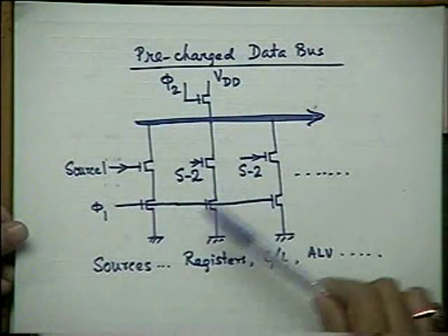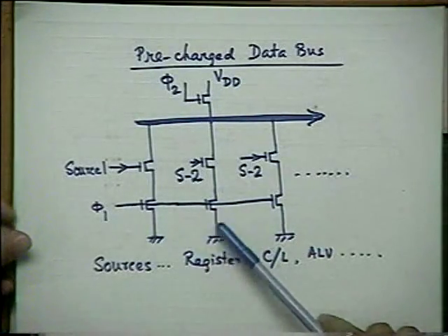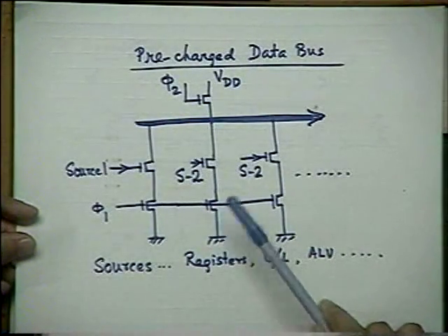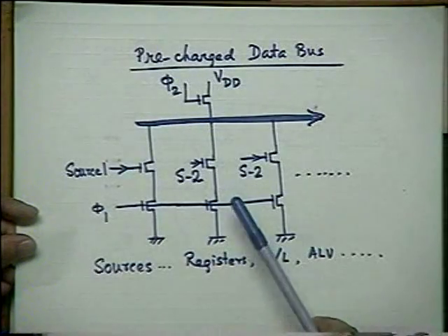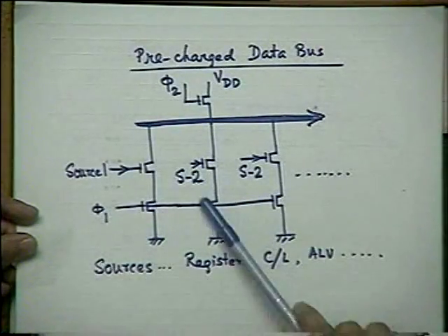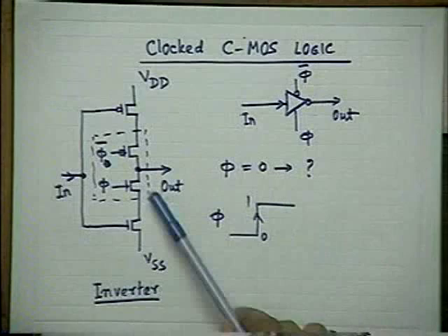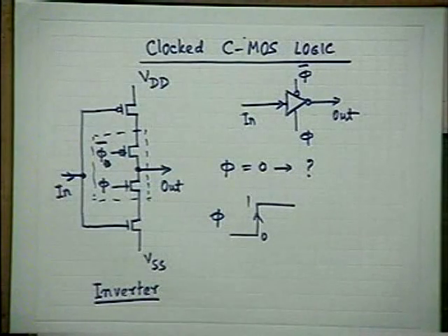But is it a very convenient way of, is it really much beneficial? Similarly, you can compare with the Precharge logic case also. Your transistor count is more in these particular examples. Whatever I have discussed in the NMOS case, the transistor count is much more than the normal static logic. Similarly here also, if you compare with the normal static CMOS logic, do you think there is any special benefit derived out of it?